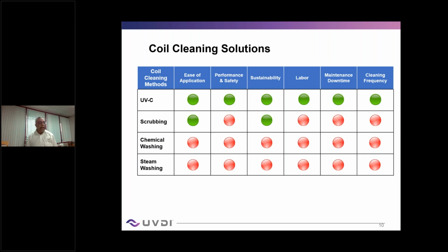Some reports actually indicate that high pressure steam cleaning can force the growth deeper into the fin pack, compressing the growth material so tightly that the only solution will be a new coil. Both methods, chemical and steam, can be detrimental to today's heat transfer issues. So coil cleaning is certainly necessary, but cannot be done economically with the frequency and the level that will keep the coil operating at a design level.